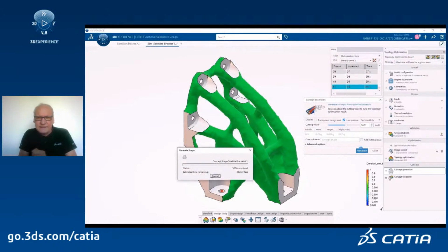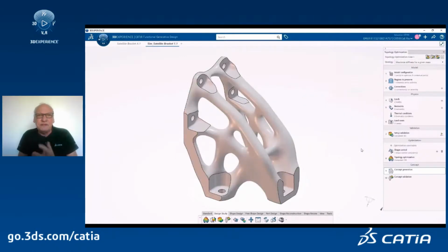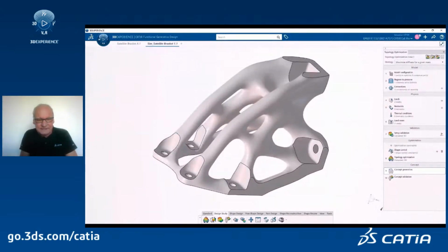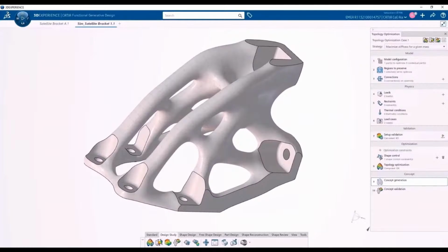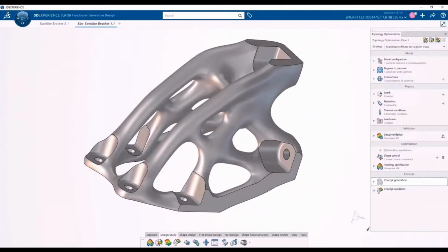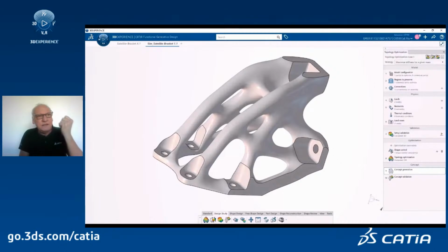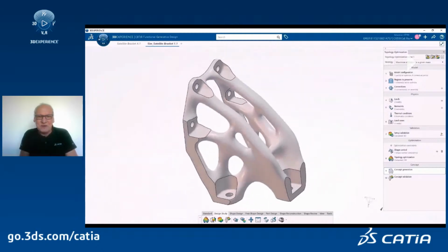And once you select, CATIA automatically computes a solid. It creates a subdivision surface on the so-called bionic shape, and reincorporates all the mechanical features like the holes and the pockets inside this automatically reconstructed subdivision surface. You see the quality of what has been done. It's quite nice. It's still, of course, a concept, but it's high quality. This is a solid, so you can mill it, you can do a drawing, you can export it as a STEP file, you can validate by simulation. It's, by the way, what we will do.